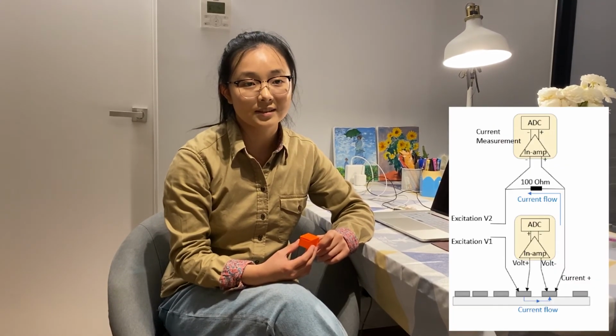When we use the SMU to characterize a solar wafer, we use a D-sub cable to connect the SMU and our newly designed Probe PCB. The Probe PCB has 12 TLM pattern probes to connect the TLM contacts on the wafer, 6 for measuring the current and 6 for measuring the voltage. Each contact has 1 current probe and 1 voltage probe to minimize lead resistance.